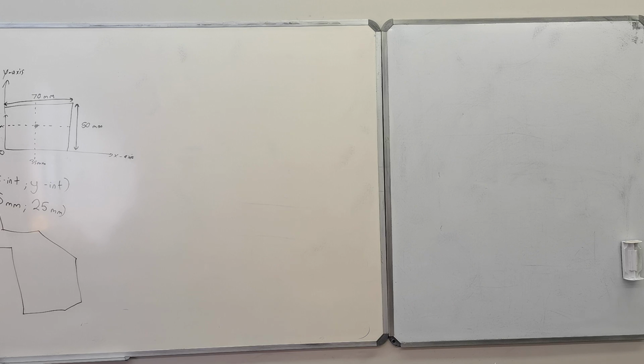So your area of the moment is equal to your total area multiplied by your center point. X bar will basically be your center point. And the moment of the area OABC about the x-axis would be area of the moment is equal to A times y bar.